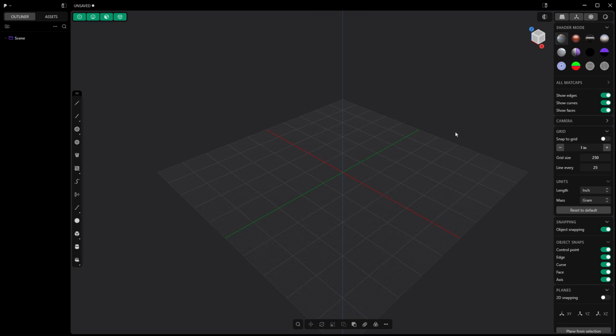Whenever we are starting to model something, it's always good to double check your units. You can enter units in alternate unit dimensions. So if you're in metric, you can enter IN for inch. If you're in inches, you can enter MM for millimeters when you're doing numerical inputs. That all aside, we're going to stick with the units that are given in an image.